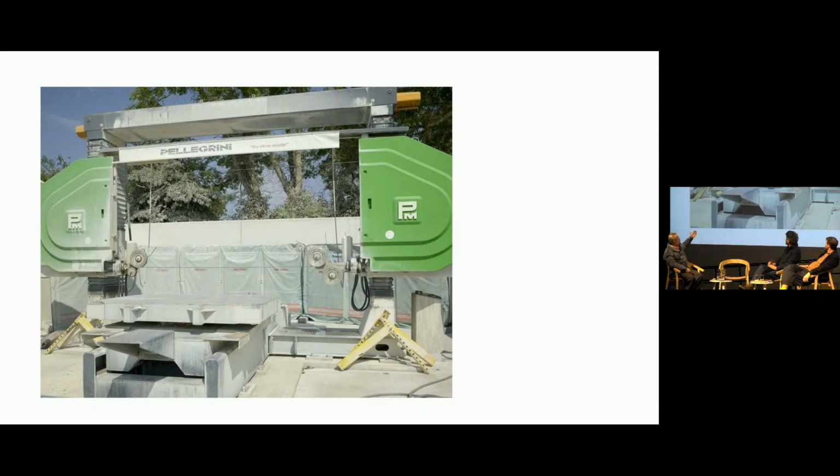The shaping is now done using mostly electricity, because in a lot of your calculations you need to have electricity rather than diesel. Yes, and it's key. So here we are using mostly electricity from the grid, and here you've got a typical diamond wire system to cut the stone, with a single loop. There's some diamond attached on that cable that turns at a certain speed and cuts your block like butter or cheese.